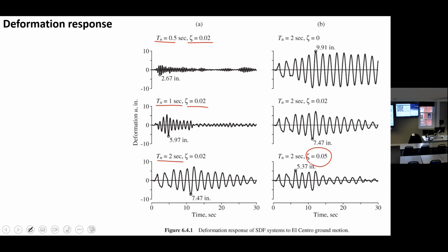So what I want to say is that damping is really a complex thing to speak about, and we can keep the damping constant for, let's say, steel structures or concrete structures. For steel structures, it's really 2-3%. And for concrete structures, we call it 5%. Sometimes for every structure, we call it 5%, because it doesn't make a big deal for what we want to do today.